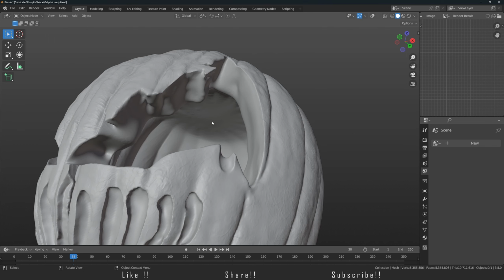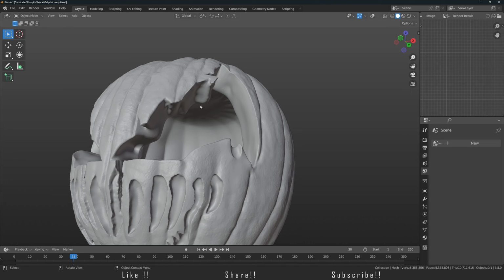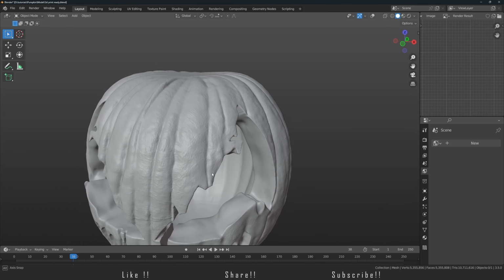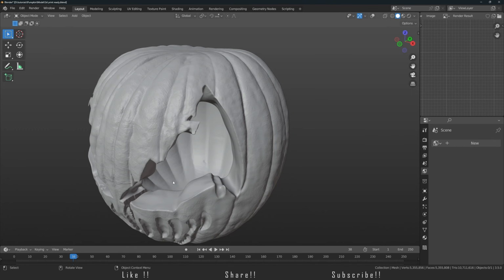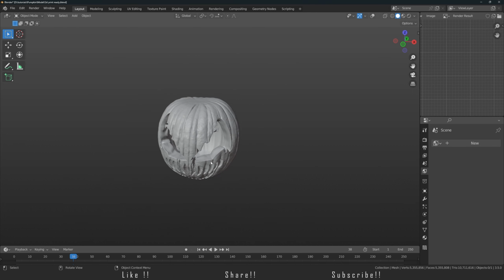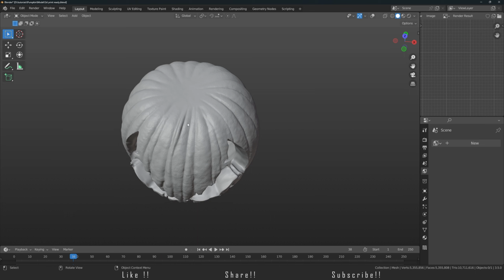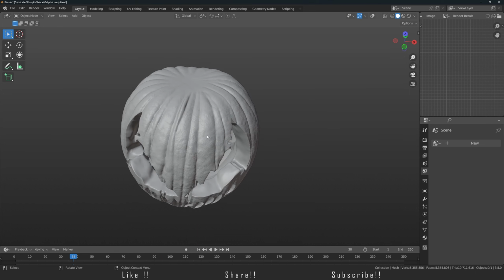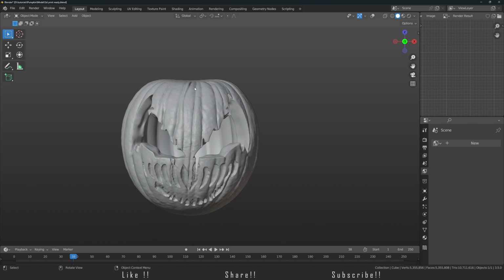And I don't want that, because if Cura were to create the support like this, it's going to be pretty hard for us to extract that support from the eyes, and there are going to be some leftovers. So what I want to do, I basically want to create a hole, and I want to make sure that all the support that Cura is going to create is just going to get eliminated. And in order to do that, I'm going to be creating a hole in the top.